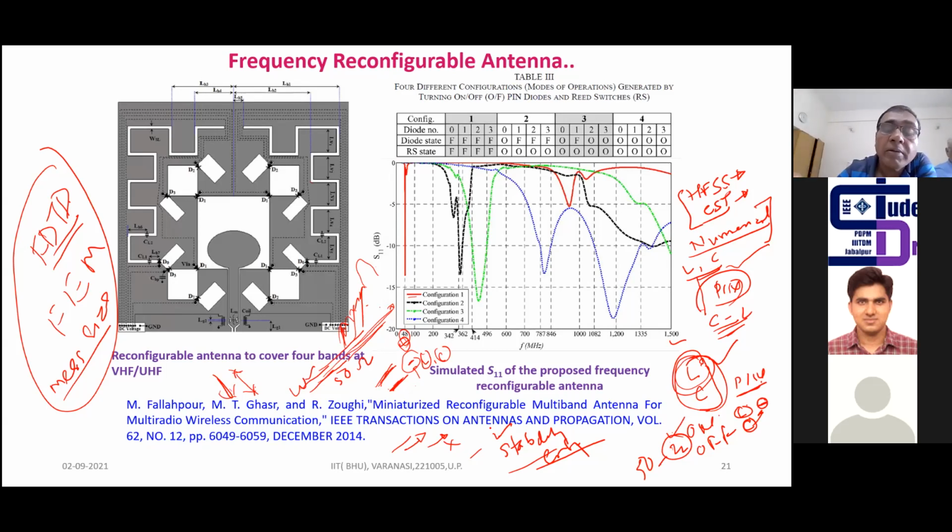Now when you are connecting this lumped element, you can see it is very tiny, almost 0.5 millimeters in width and 0.5 millimeters in length. Once you plot the mesh, you can see whether the tiny structure is fully covered with proper dense meshes or not. If it is not, the solution is not converged properly. So you can choose particular components and define the mesh size less than 0.5 millimeters so that proper meshes can converge there. These are the things.